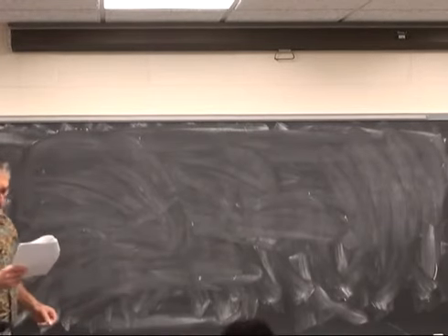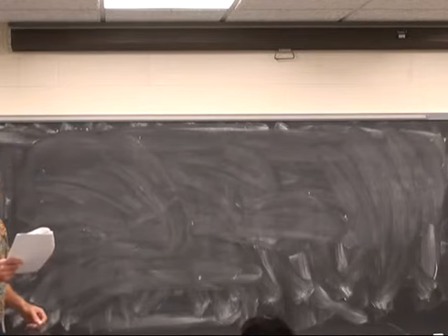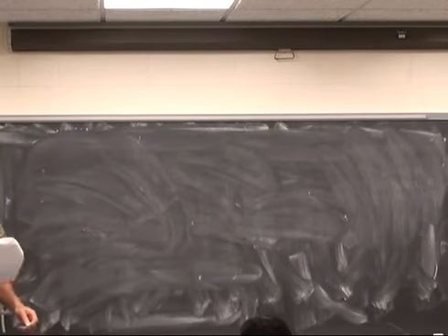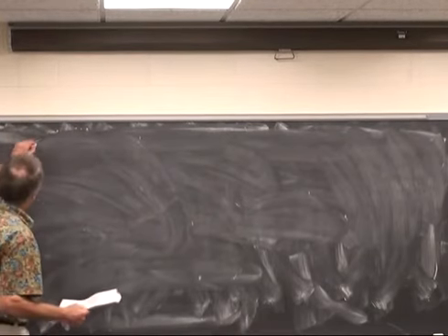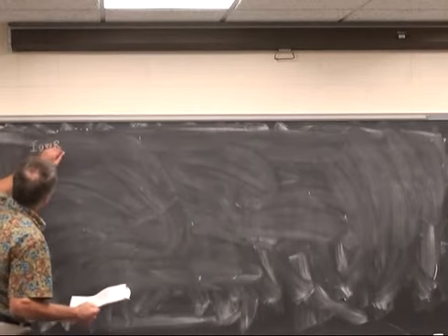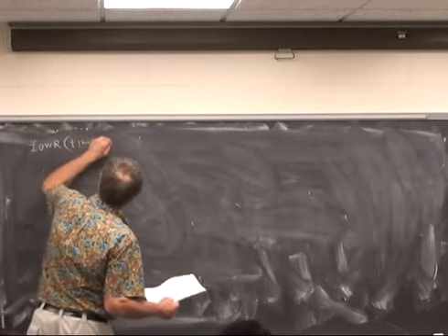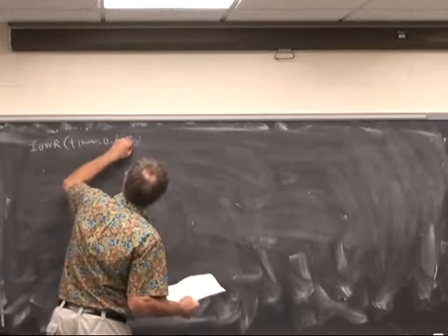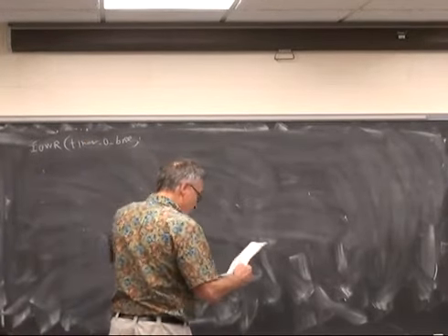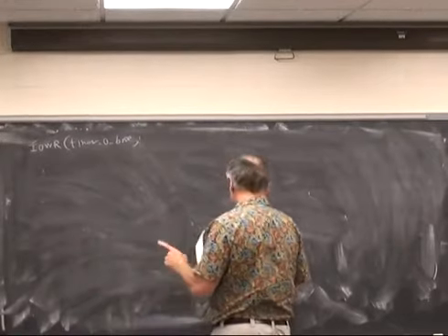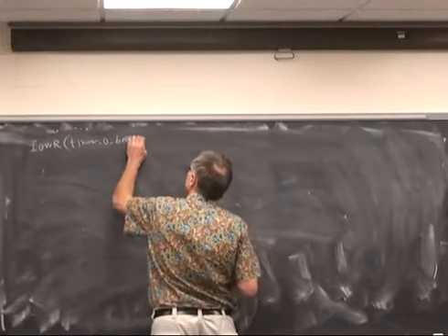The long form is IO write Altera Avalon timer period low, or we could just write IO write timer 0 base. The offset for the low period is 2.